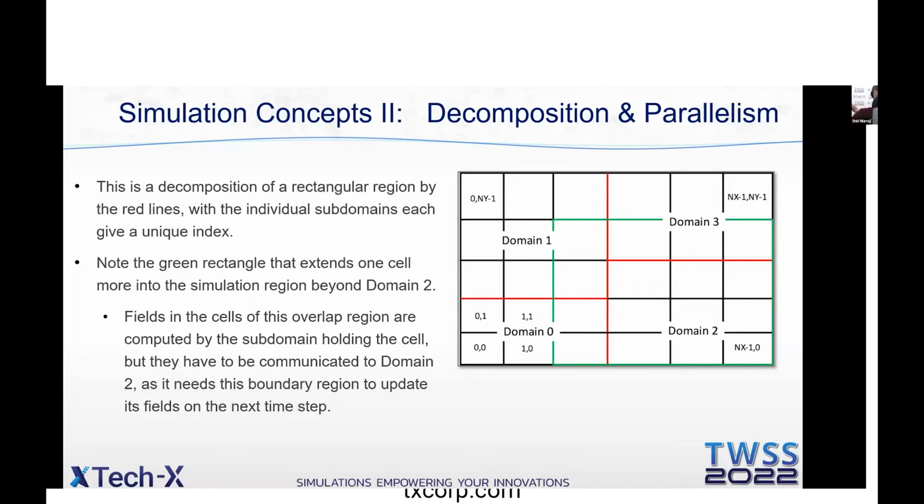And so this creates a communication condition for as many additional CPU tasks as you want to create. You're going to create additional overhead because these cells are going to have to communicate back and forth with each other. This is an indicator for people that are maybe new to parallel computing. If you have a domain that's only 100 cells, you might actually end up slowing down your simulation if you split that across 32 cores instead of running it across just 2 or 3 or 5 or 6, some smaller number. So the key here is you can in fact create more work for your computer if you break up your subdomains to be too small. That will actually slow down your simulation run.